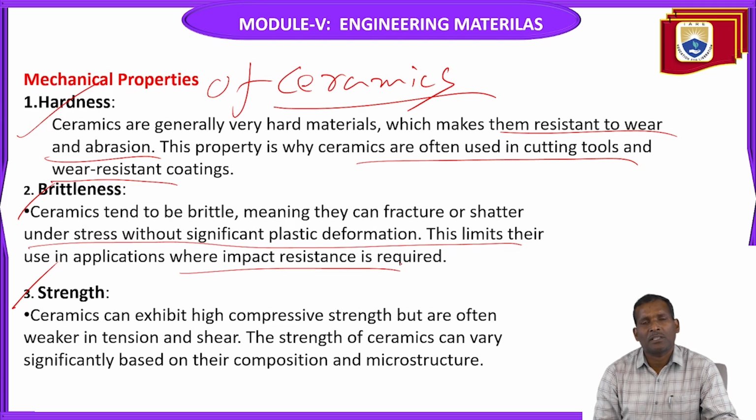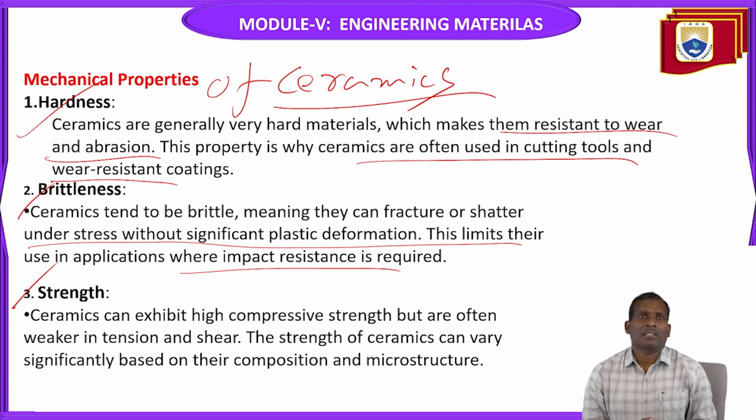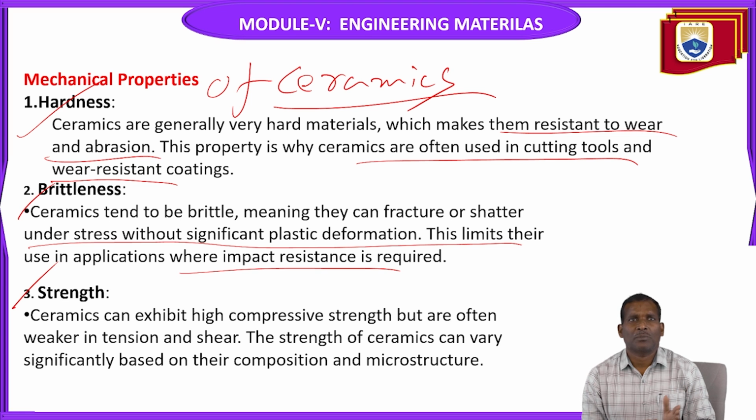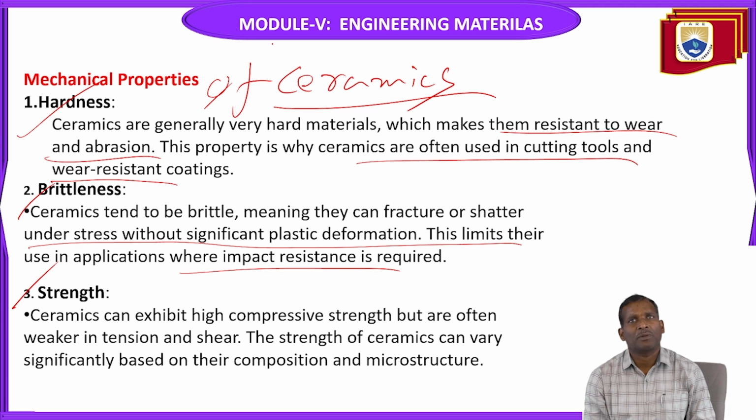Plastic deformation means the material has the plasticity property. Whenever a component is subjected to some load, a brittle material does not give any indication of deformation. Suddenly it will fail, then it can fracture. So wherever impact resistance is required, these ceramic materials are not suitable.